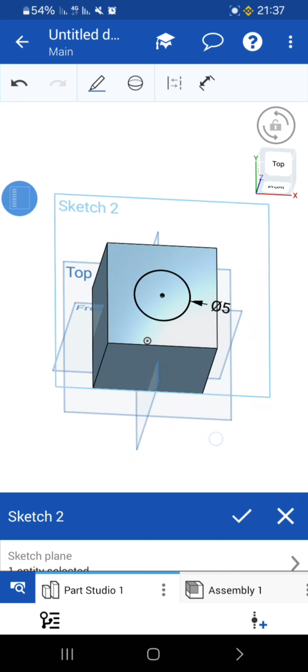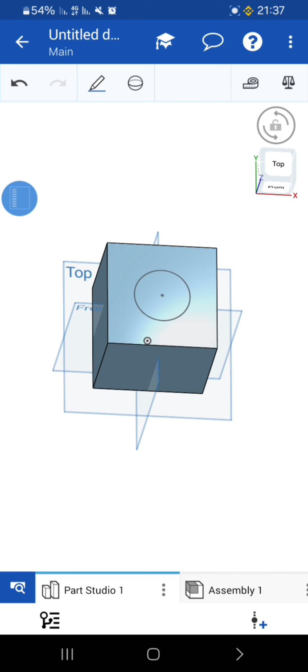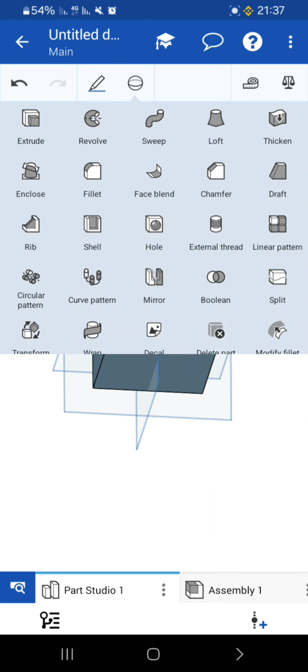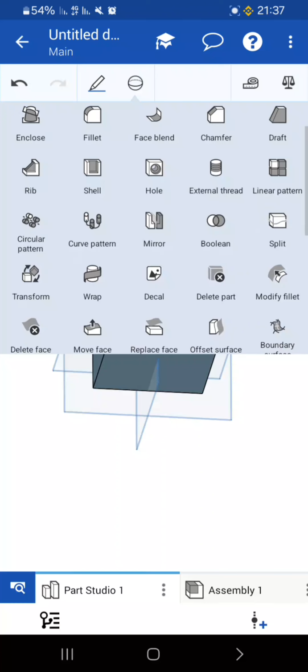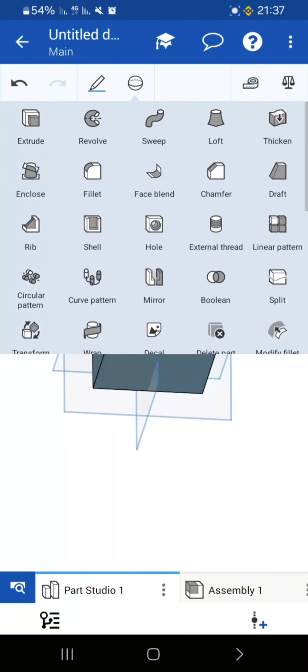To do the perforation, we can use the extrude tool. We select the circle by clicking inside the circle. We click on the ball icon. As we see, there are many tools related to 3D objects such as sweep, loft, and tools to repeat objects and add a plane, and others. We will also explain them in the upcoming videos.